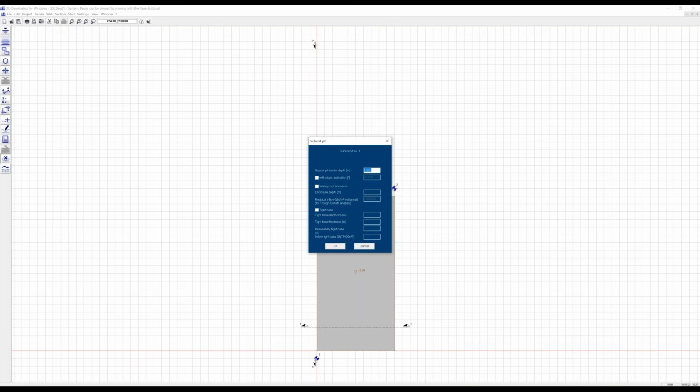analysis methods. One option is a waterproof enclosure. So there might be a sheet pile wall around this foundation pit, which reduces the area of inflow for the water. So there is one diagram in literature how the inflow to the wells is reduced only if the wells are inside of the foundation pit. Otherwise, this won't help.